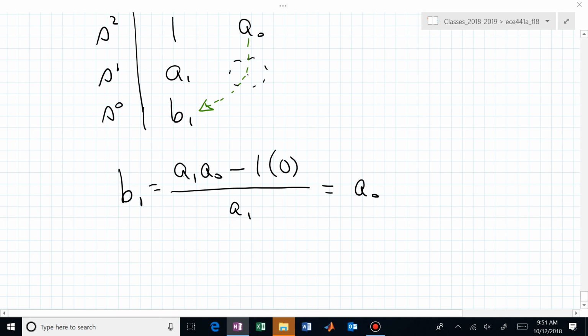So what are we going to do? Well, now we have a completed Routh array. We need all of the leftmost entries to be positive, to be stable. That means A1 is 0 or positive and A sub 0 is positive. I'll fill that in after class. But you can see that we've now validated that Hurwitz test is necessary and sufficient for a second order, and only a second order.